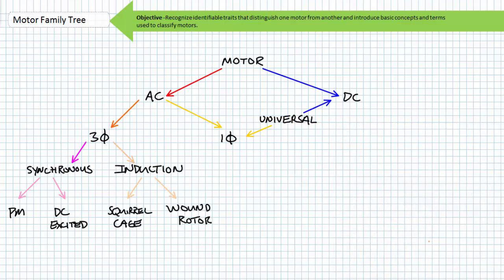Long story short, if your three-phase AC motor has two connections to the rotor, chances are it is a synchronous motor, and those slip rings are the positive and negative connections for the DC energy used to electrically excite the rotor electromagnets. The windings on the rotor might also be visible. Speed should be constant for a given operational range. If your three-phase AC motor has no electrical connections to the rotor, and you can see permanent magnets on the rotor, chances are it is a permanent magnet synchronous motor. Speed should be constant for a given operational range.